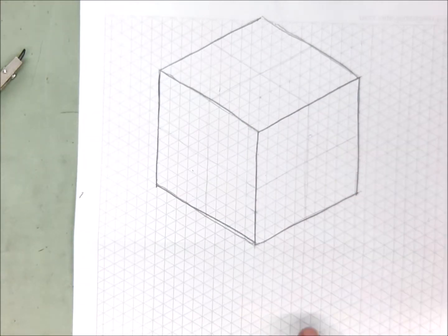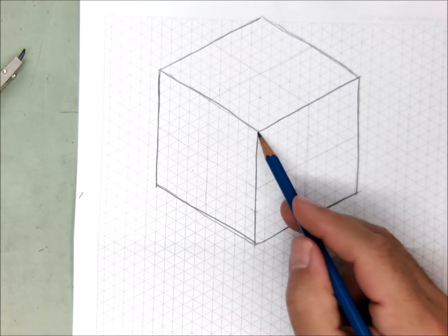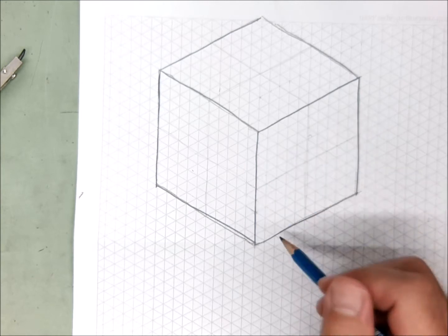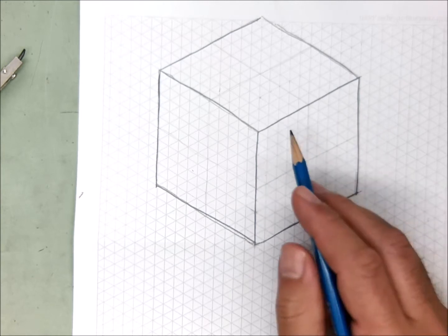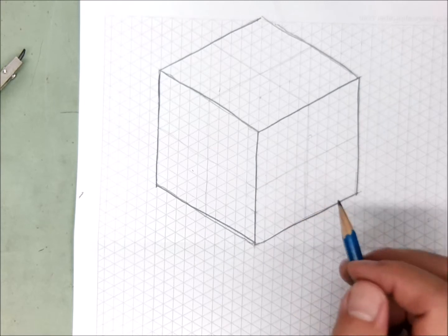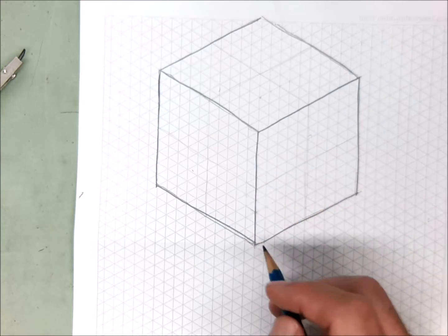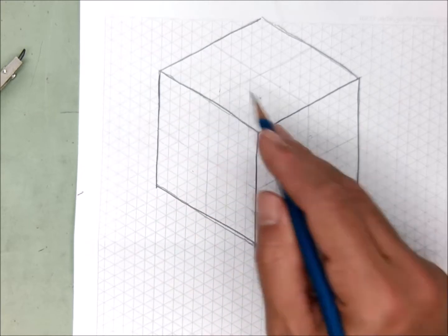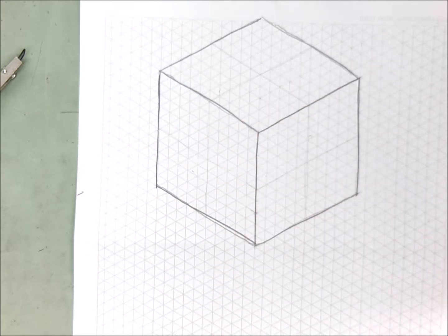So what we're going to do is, I made a cube here, and there should be enough room on your isometric graph paper. If you make a cube that is 8 by 8 or 10 by 10, no bigger than 10 by 10 though, but make sure it's a cube and all the sides are the same size. All right, and again, I started out with a chicken foot and went up 10 and over 10 and over 10 and created my 3 surfaces for the front, top, and side.